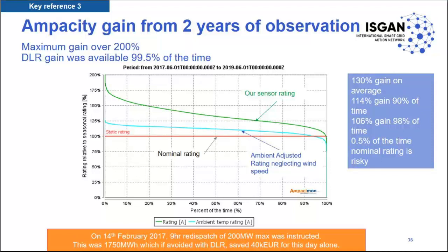The question is, how does this help to reduce grid congestion? This line Bill Ost, as stated by the German regulators report, is often congested and causes the need to redispatch. The redispatch rule in Germany dictates that the most effective power plant to solve the congestion should be called to change its output, which are typically the power plants in close proximity to the congested line. In this case, there are a few power plants connected at the north end of the line, which are often subjected to downward redispatch. The redispatch information can be seen on the German grid transparency platform called Netztransparenz on the web.